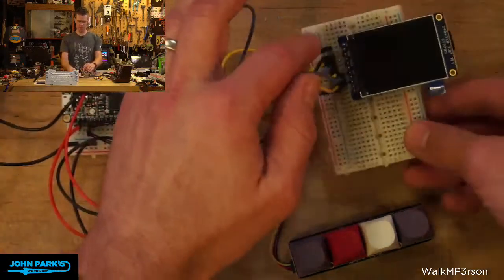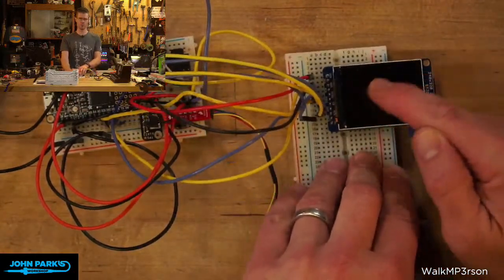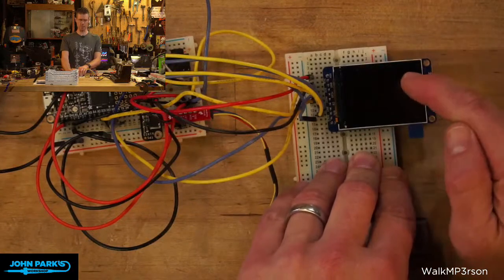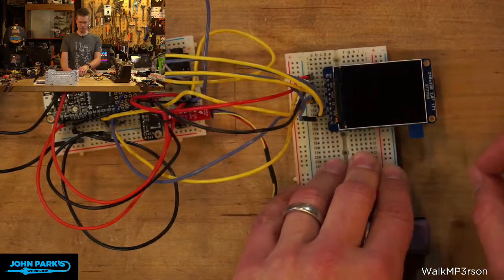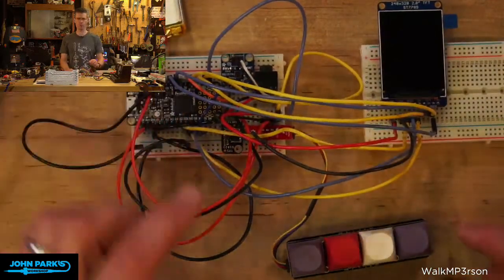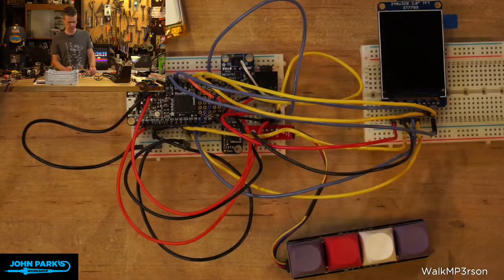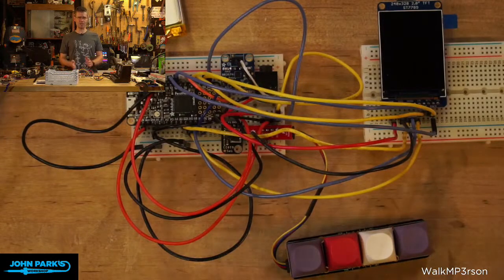Eventually I'm going to rotate the display sideways, and I'll put, I think, a cassette tape icon, maybe with some animation of it moving, and the name of the song and the mixtape kind of as tape labels. That's the goal here. I'm really excited because the Feather M4 is a great board for doing this, except it doesn't have much memory. It has 2 megs of space on it, so you can't really get that many songs on there of any quality or length. It helps that I'm doing mono, but now with the SD cards I could do bigger files and stereo files. So let me do a quick demo of this.